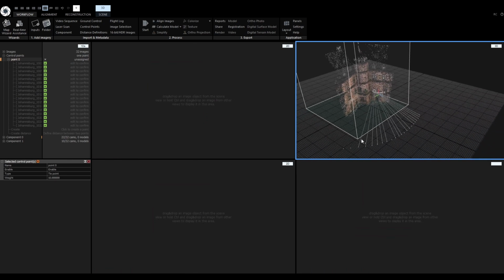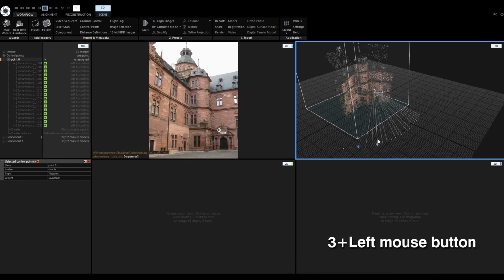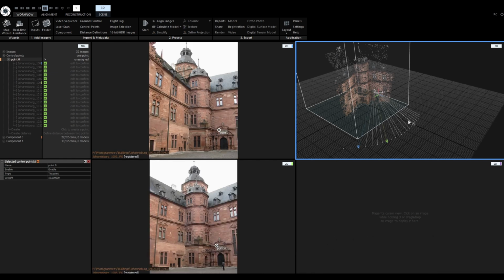These gray relation lines in the 3D view have their meaning. You can see the angle between cameras that can see the control point. You can even assign color cursors to these lines. To do so, disable the control point tool by pressing F3 and assign cursors by pressing numbers from 1 to 4 and by clicking on them at the same time.